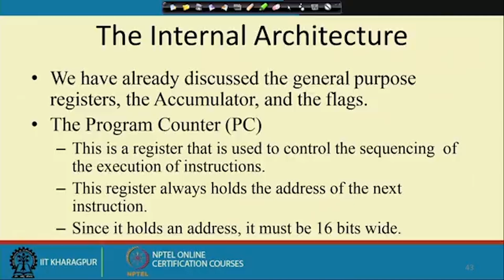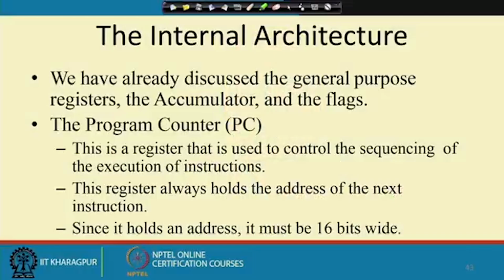Since it is holding the address, and the address can be in the 64 kilobyte range, it has to be 16 bit wide. That way I can have this program counter register. It will be doing the sequencing of operation.